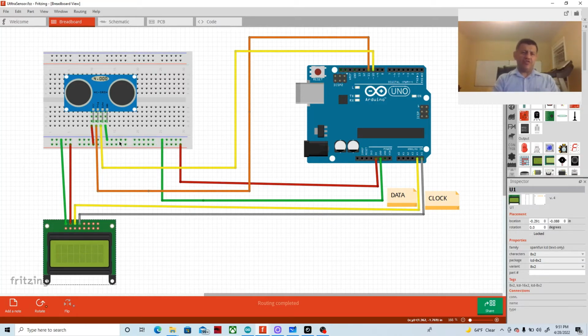Now, the sensor right here: this is the ground pin, I go to that pin right there, and this is the hot, which is the positive, this is the negative, to be more clear. I am talking in general purposes. When I mean hot, I mean positive. So this is the 5 volts going over there, positive 5 volt going to VCC.